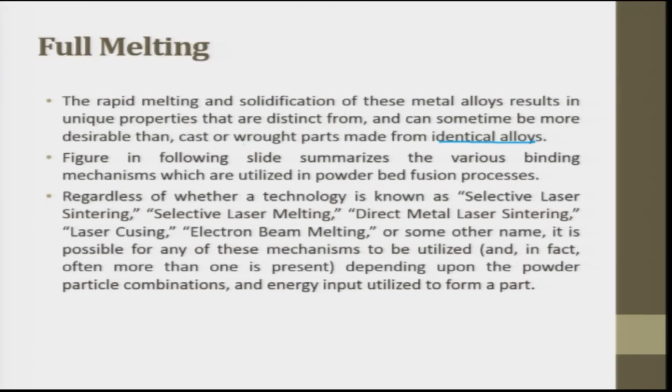In the next slide, we will show the summary of the various binding mechanisms which are utilized in the powder bed fusion process. Regardless of whether a technology is known as selective laser sintering, selective laser melting, direct metal laser sintering, laser fusing, electron beam melting, or some other name, it is possible for any of these mechanisms to be utilized depending on the powder particle combination and energy input utilized to form a part.